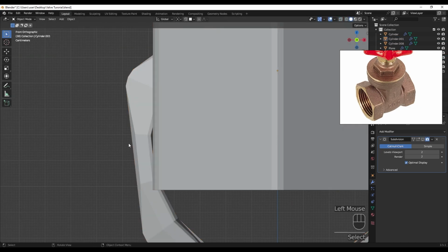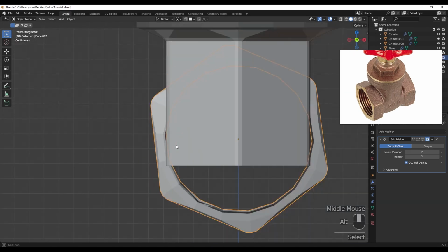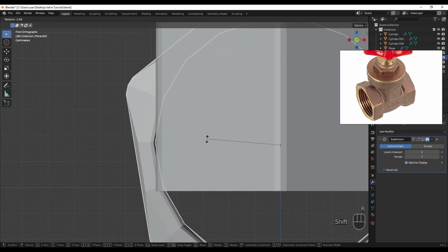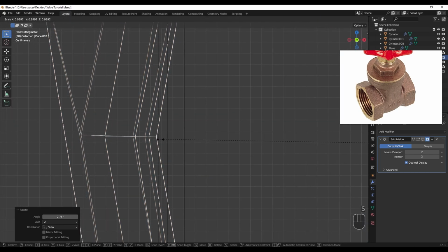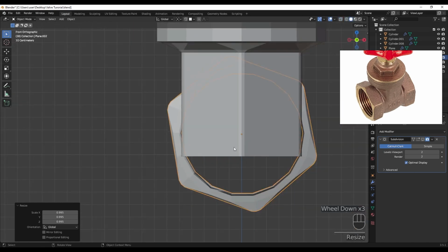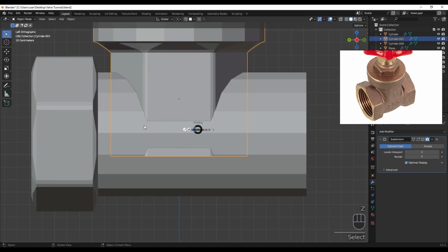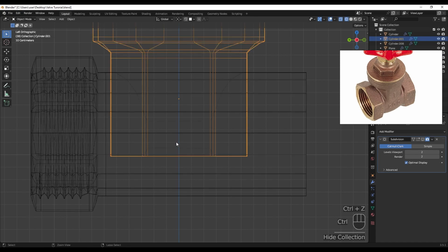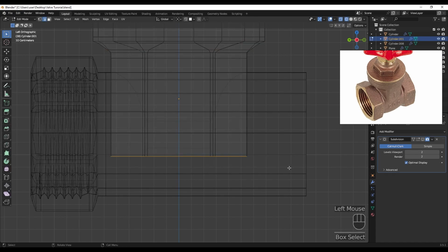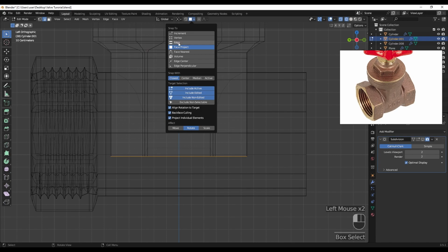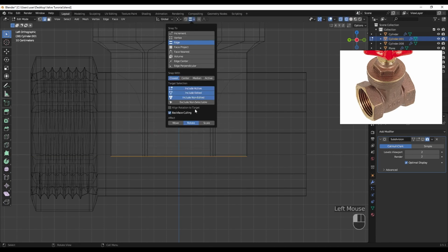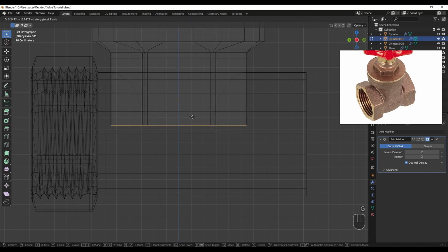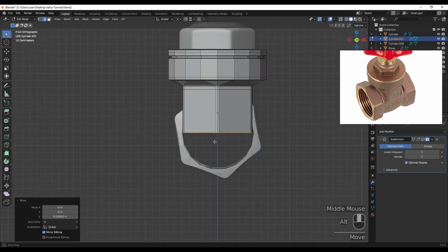So now we need to connect these two together. So before that, let's do a little adjustment for this to make them closer to each other, like so. All right, now we can operate the Boolean modifier, and before that, we can select these faces and put this on the edges and press G, Z, and let's put this on move and G, Z, and here we are going to snap.